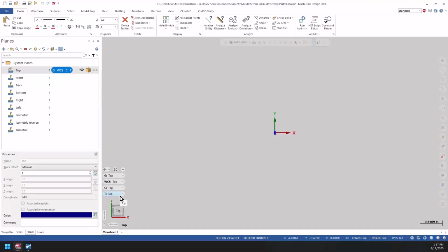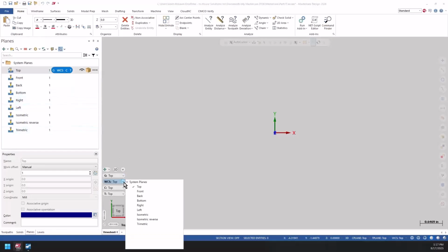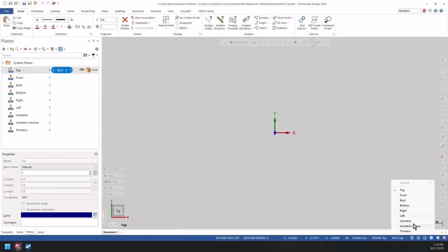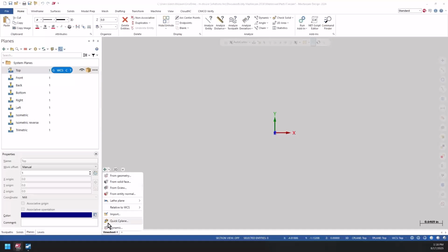This is a lot better because it's integrated within the group system. So if I open, let's say, my WCS here, I can actually minimize and expand the groups that I see here, something that I'm not able to do from this menu here. So it's actually a lot better to use this, and also you have access to creating all your planes from this menu here and change if you're set to 2D, 3D, and you have access to your settings here.